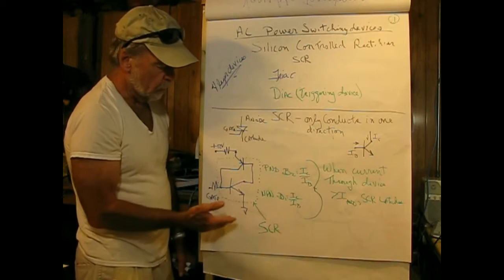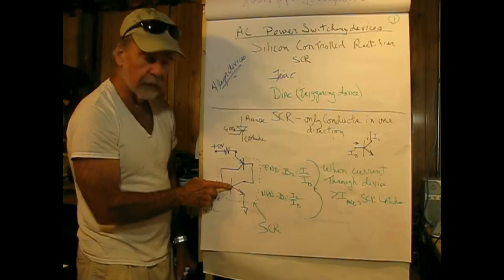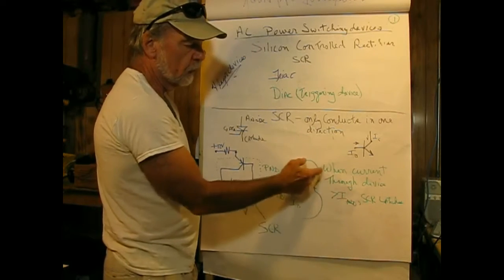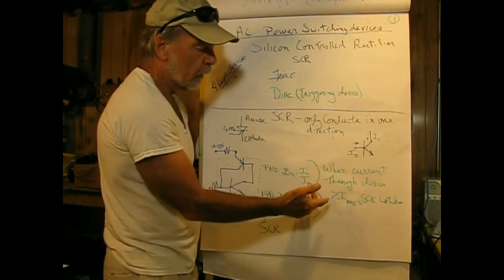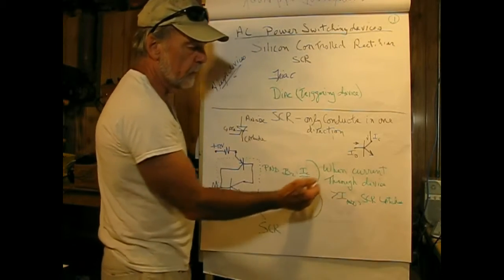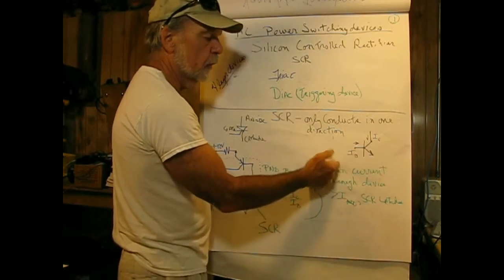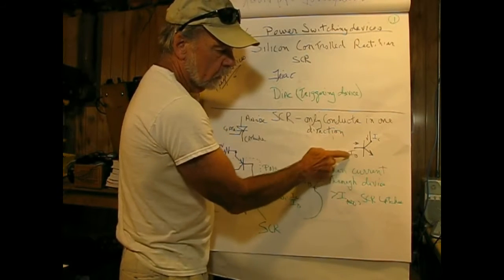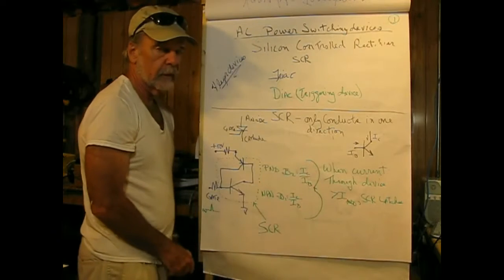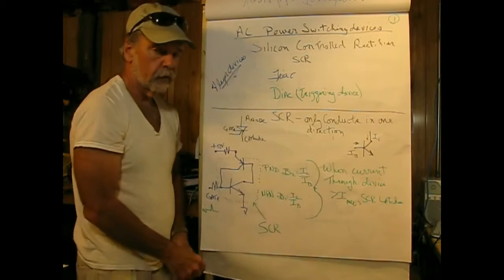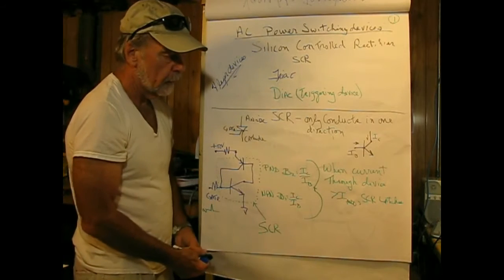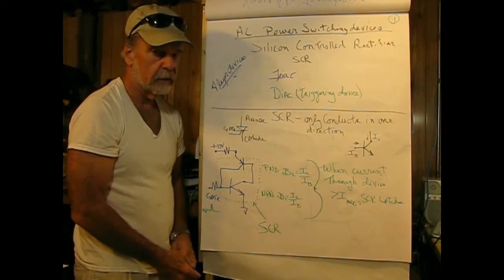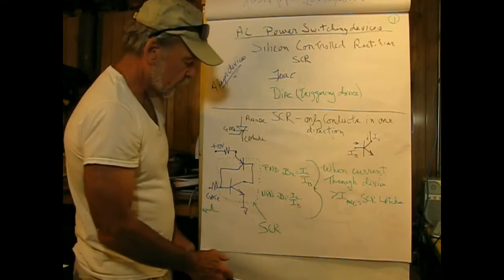And what we need to note here is we have two transistors. Note that this is an NPN and this is a PNP. And what we need to know about this is that the current gain, called beta, or in H parameters, it's HFE, forward gain common emitter, but the collector current is beta times the base current, and that can be a significant increase. For example, in a 2N3904, the beta ranges from 60 to 300. Now, it's also highly dependent upon current. So that's kind of the secret to it.